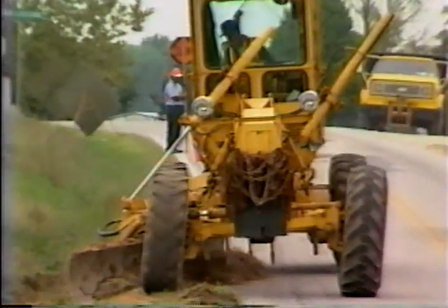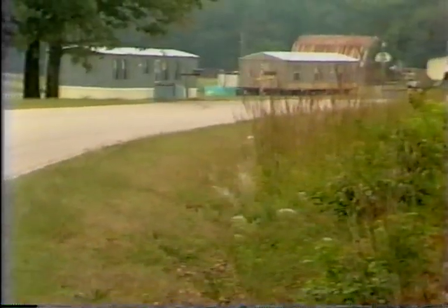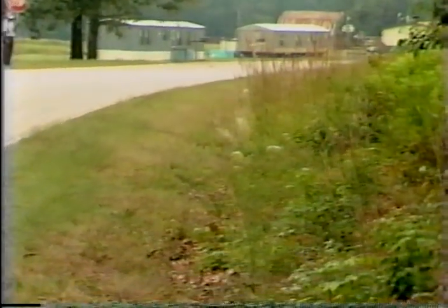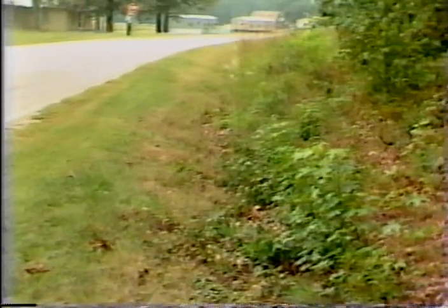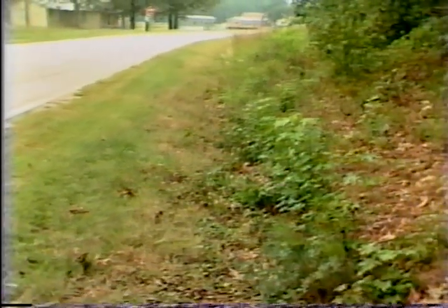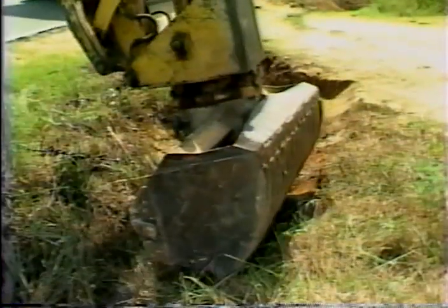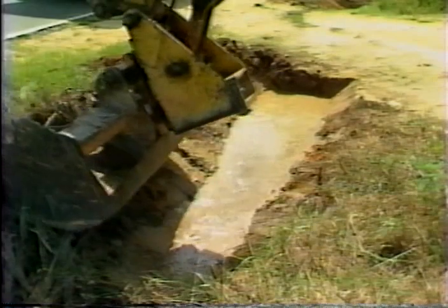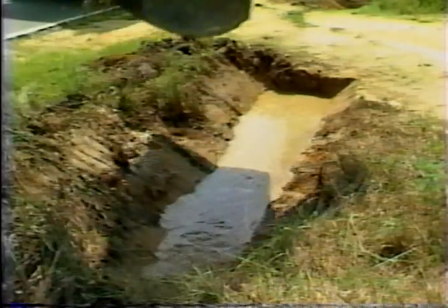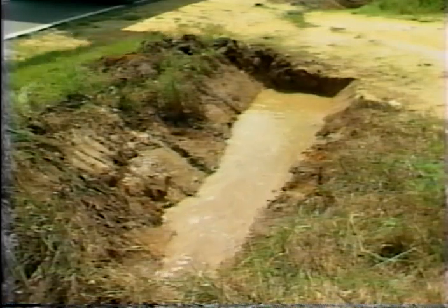First, let's discuss ditch maintenance using a motor grader. Use a motor grader for long ditches that are uninterrupted by driveways and pipes. Here, the motor grader can operate for a long distance without delay and do a more efficient job. Do not use a motor grader on short, wet ditches. The motor grader does not have the maneuverability to do this job efficiently, and wet areas cannot support the weight of the motor grader.